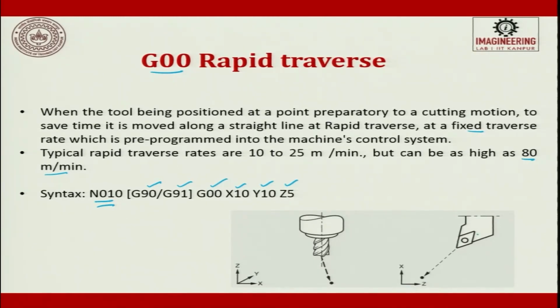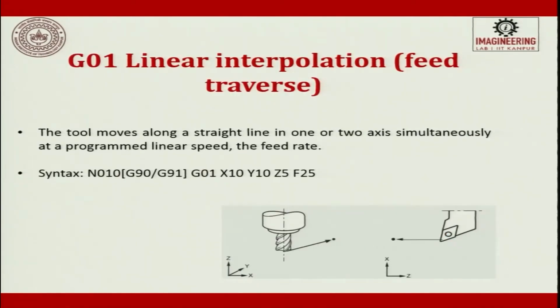When we do this on a turning operation, it can be with respect to the nose radius, which you have to define beforehand, or with respect to the center of the tip or the periphery of the tip. Depending upon the tool register you have set, you change the center point accordingly. You have to look at how the machine takes the reference points. If it takes it for the periphery, you give these points as offset. If it takes it for the center, then the diameter or the radius is given as offset.